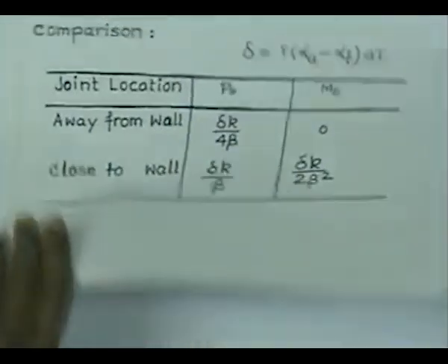And this prevention of the radial expansion always gives rise to more forces, and that is what is demonstrated here. In the case of thermal stresses, thermal forces also, or forces arising out of thermal expansion, you will find that they are going to be always higher if you are trying to arrest the thermal expansion, and that is what is actually demonstrated in this table.